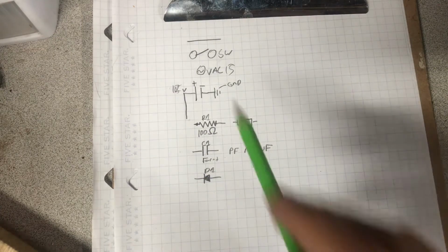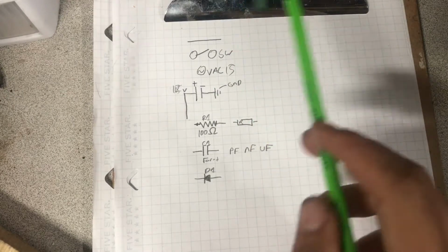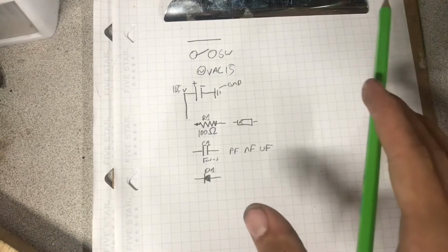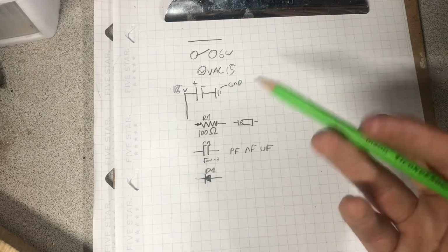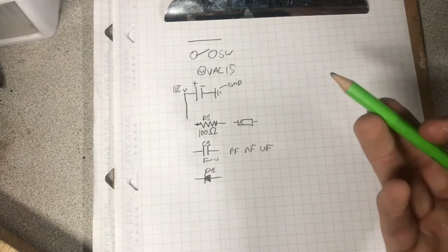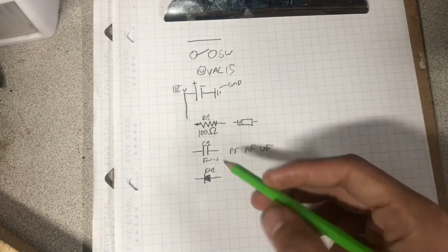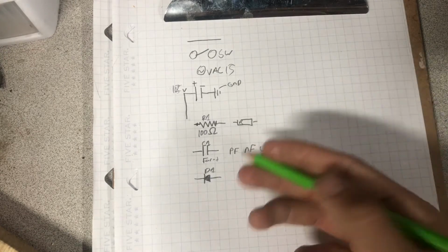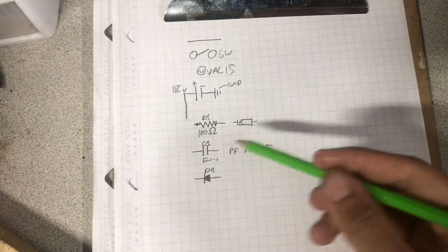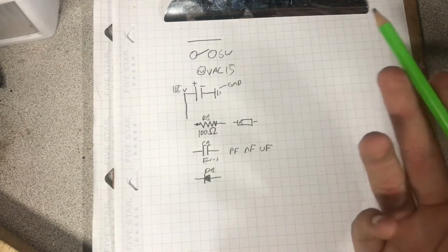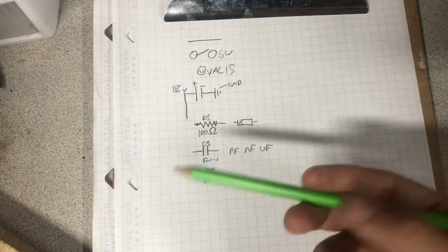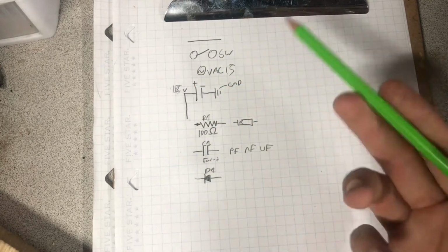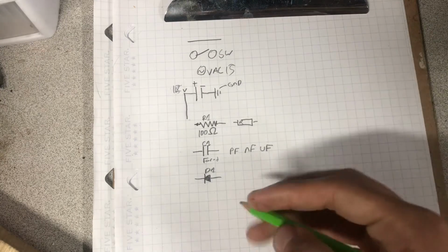So they're often used to change AC to DC, because AC is alternating current and DC is direct current. With AC, the current changes back and forth 60 times a second in the US or 50 in Europe, or 60 hertz would be the correct way to say that, right? So you transform that into DC with a diode, or say a bridge rectifier, which is made of rectifier diodes. A bridge rectifier is 4 diodes in a specific arrangement, right?